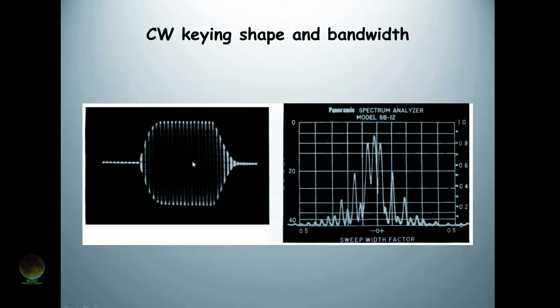I'd love to. So when you're sending CW, the issue is how quickly does the RF come on and off? Is it clean, clear, well-sounding CW? So the rise time and the fall time are kind of critical. New radios are just really perfect about this, but the old rigs sounded pretty bad. I did work someone on 40 meters about 3 years ago, and man, key clicks everywhere. And I worked one about 10 years ago, and the sound in my headphones was dwad it, dwad it, dwad. And I thought, man, voltage regulation.